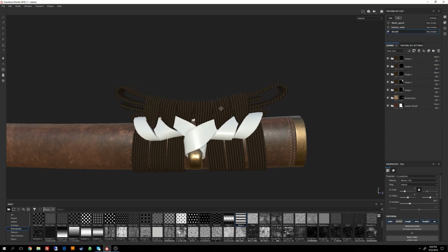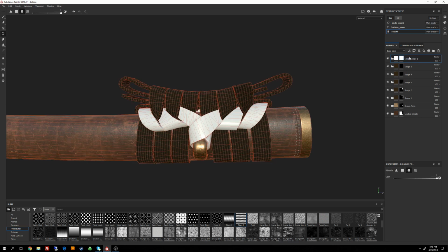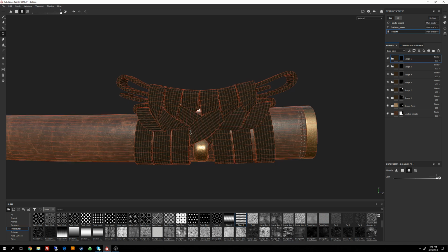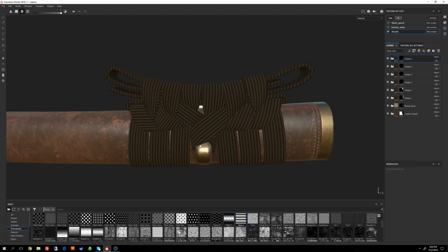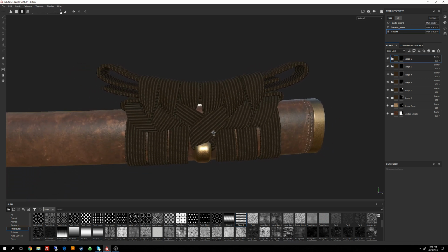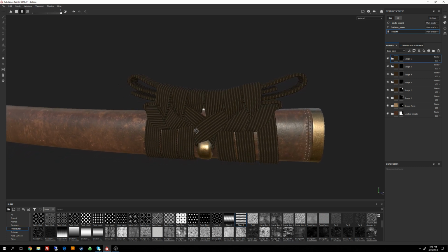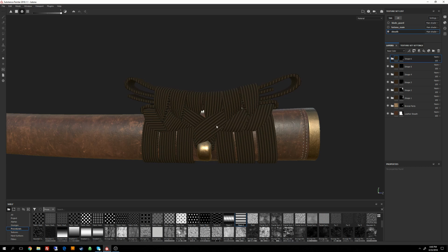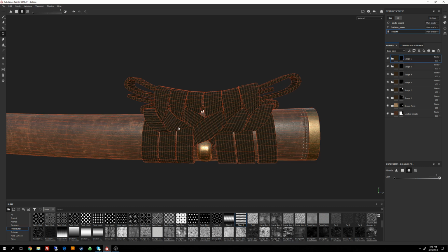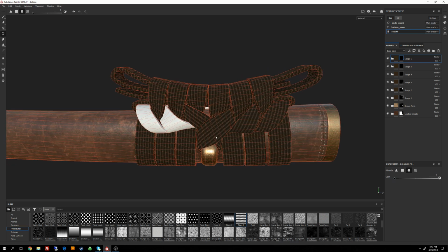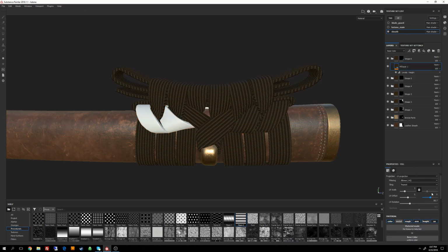So let's see how these respond now if we mask them all together. So I'm going to go ahead and duplicate this, rename this to strap 6. We put a space there. Our mask, and select this geometry in here. Might be able to get away with the middle one. I'd be able to get away with all 3 of these actually right on this side. You just deselect this side over here. So we're working. There we go. Wasn't wanting to select there for a second. All right. Now let's see if we can adjust this rotation a little better.